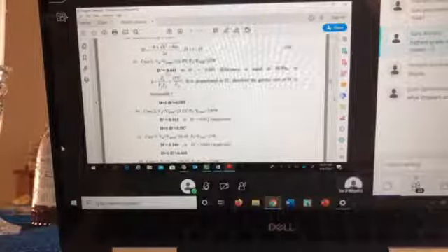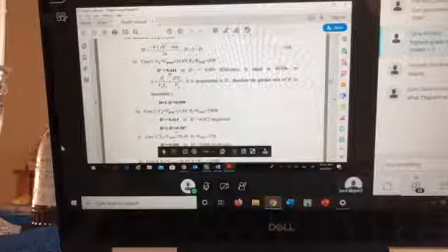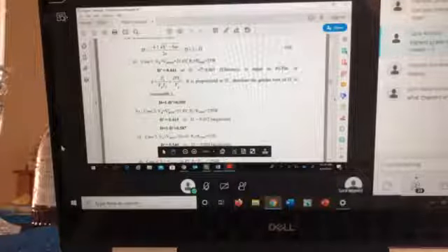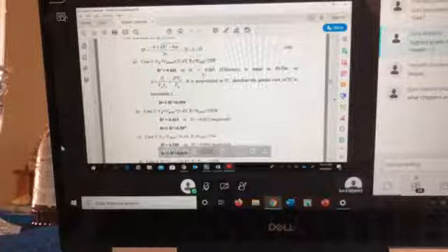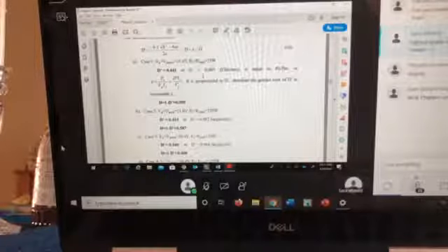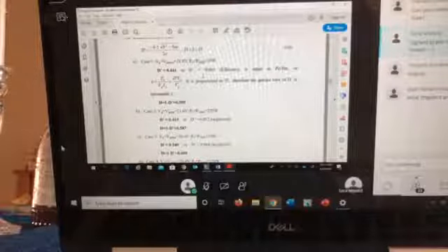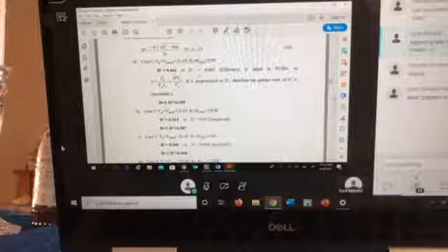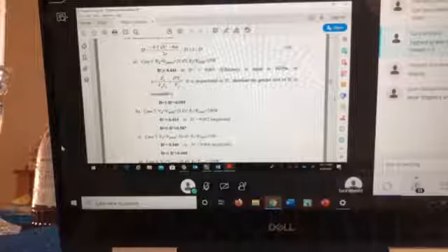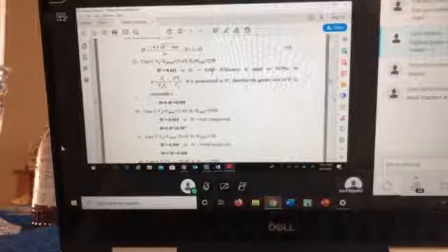And as you can see here, you have 2 values. A value that's about 0.5, or 0.4 to 0.6, and a value that's very, very small. So this value that's very, very small for D prime means what? It means D will be on all the time. Can you do that? Is that possible? If the duty cycle is always on, then you're just short-circuiting the circuit. You're not really going into subinterval 2. So when you find those 2 numbers, you have to choose the reasonable value and neglect the other one.